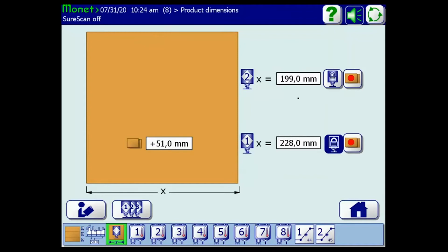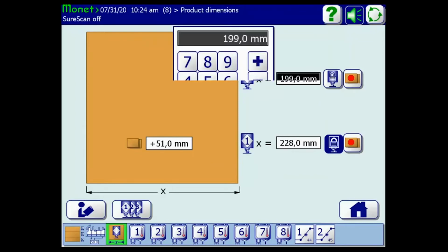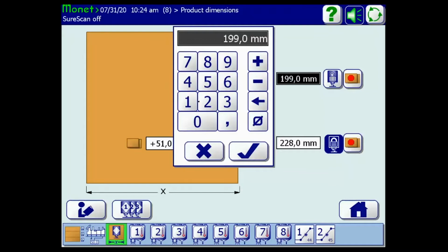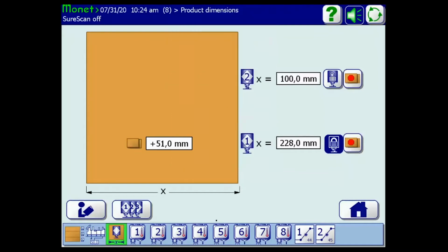But if the first carton did have a problem, if it was skewed or if a panel ripped off and you didn't read a proper length, let's say, for example, trigger 2 didn't learn the proper 200 millimeters, it only saw 100 millimeters. Well, all of my stations that have trigger 2 assigned to them, glue guns 5, 6, 7, 8, are all now failing because I learned 100, but now it's seeing 200 on every piece going through.